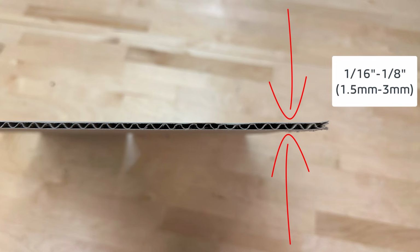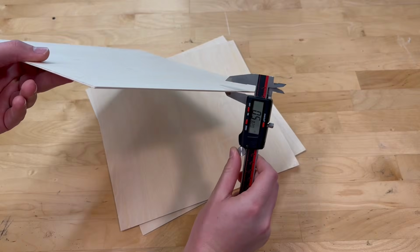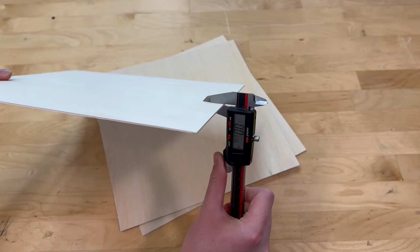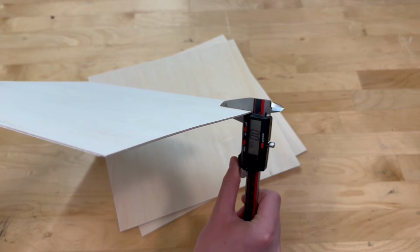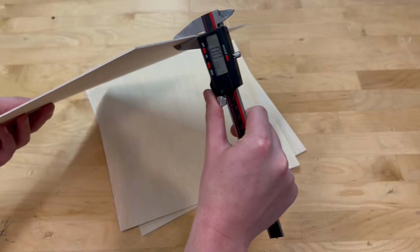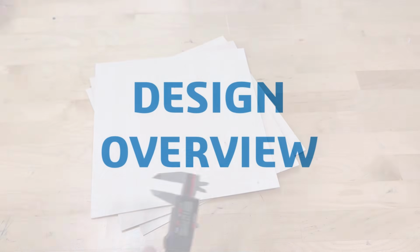For this project, a material thickness between 1/16 and 1/8 of an inch, or approximately 1.5 to 3 millimeters, is ideal. Make sure to accurately measure your material thickness. Using a pair of calipers and taking multiple measurements at different points, then calculating the average, is a good start in determining an accurate thickness value.